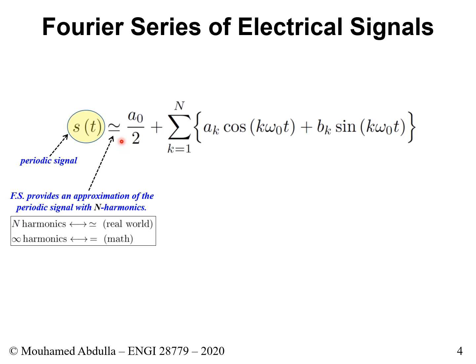And we put this because we are only taking n harmonics, right? So whatever you have here, they go hand in hand. If you have infinity here, then you put equal here. But if you have approximation here, then you put n. N is just some specific integer number. And like I wrote to you here, Fourier series provides an approximation of the periodic signal with n harmonics. So we consider n harmonics, we put approximation.